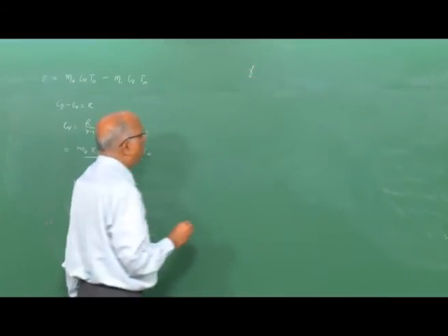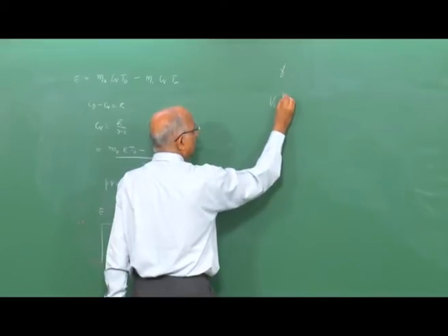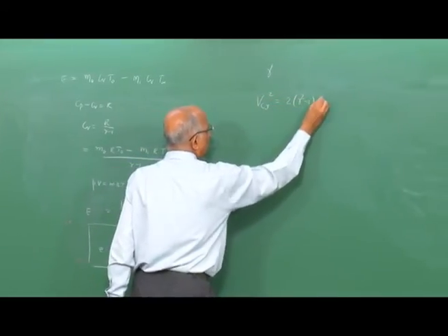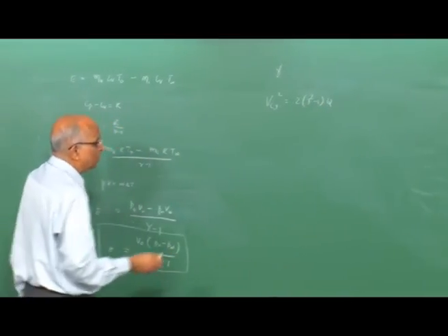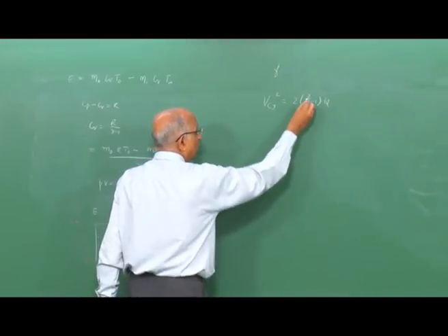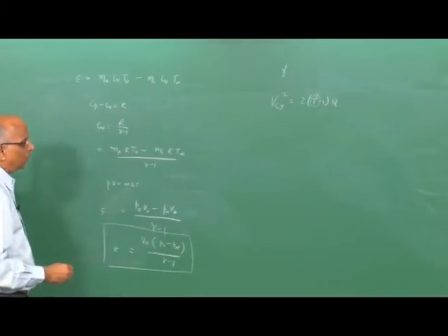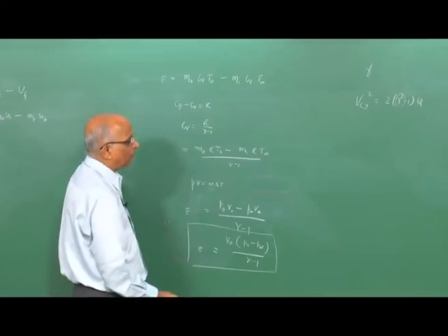If you go back and see the Chapman-Jouguet velocity for a detonation, we also got it as equal to the square root of 2 times gamma squared minus 1 into q. There also it was a strong function of gamma. We found that gamma changes between unreacted gas and reacted gas, though we took it to be common, but here also it is sensitive to gamma. Therefore, it is necessary to be a little more clear about what factors affect gamma.